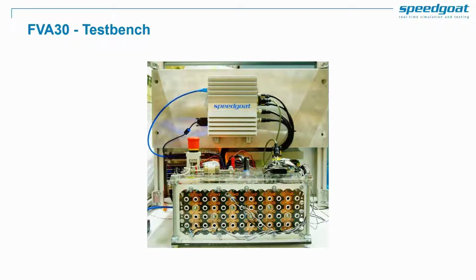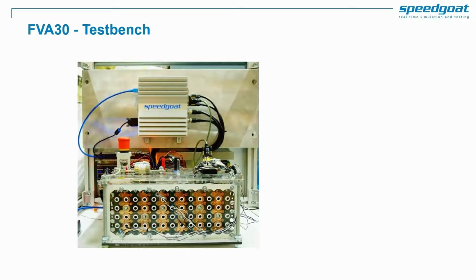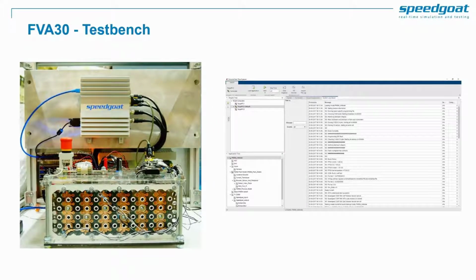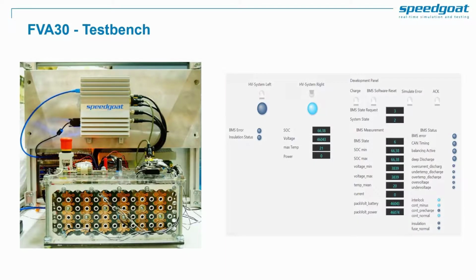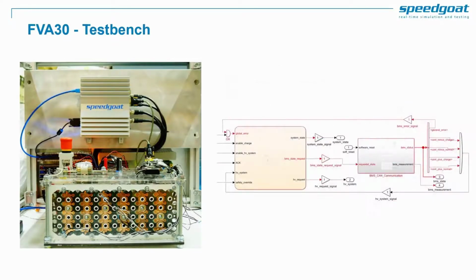The battery management system observes the state of charge and battery's temperature, for example, to ensure that the batteries are in a safe state before, during, and after the flight. To do this, the team used the Real-Time Explorer to keep track of the system state. This information is regularly sent to the main controller, which can provide the pilot with the necessary information and warnings. This was done using a graphical user interface. The system was modeled using Simulink Real-Time, which enabled them to build a model of the system within a very short time. This shows how your research project could benefit with the Speedgoat test system.